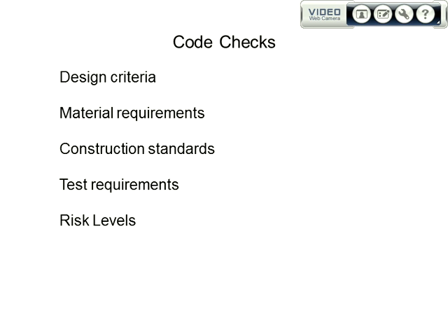It's been transporting natural gas at 75 bar. So you've got to work out that proximity distance, and then, having decided what operating pressure you're going to go for with the CO2, you've then got to decide what the proximity distance will be for its use under CO2. And to do that, you're going to have to go to the 8010 code.